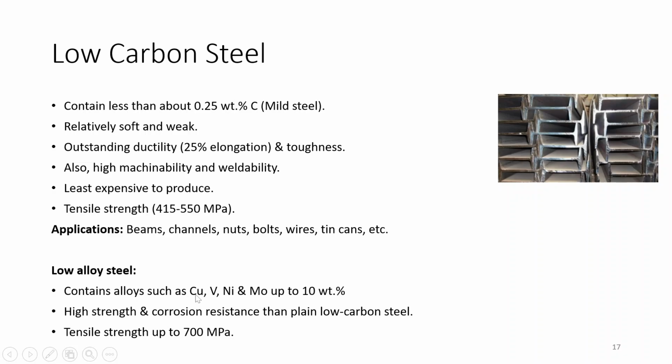Okay, so these elements, nickel, chromium and copper, these three main elements provide good corrosion resistance. Next, the tensile strength for these is up to 700 MPa. So you can compare here, from 400 to 700 MPa. This much increase will be due to substitutional solid solution strengthening.